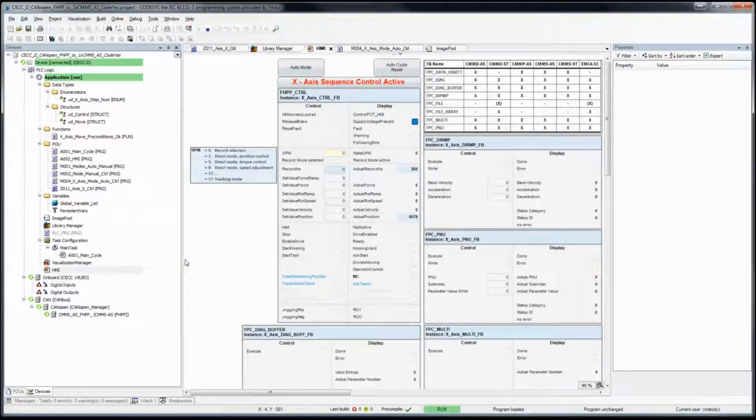It is running. So at this present time, I do in fact have the minimal I/O active, meaning I have the digital input 4 and 5 active on the X1 connector. The X3 connector at the bottom has a jumper in it, so I don't have to worry about that. That's the other channel to the DIN4 power stage enable. I have 24 volts on the top, as well as 120 volts on the top supply connector. And of course, I've got my motor and encoder hooked up. So this is the first thing you look for: supply voltage present.